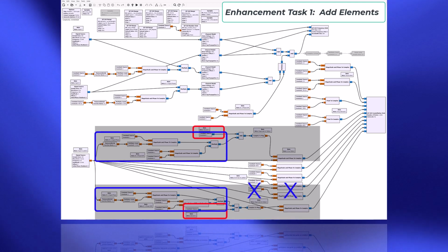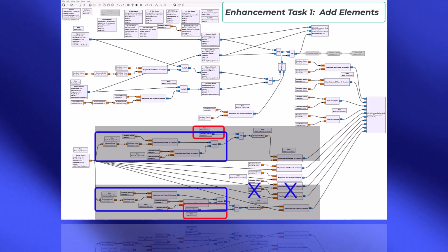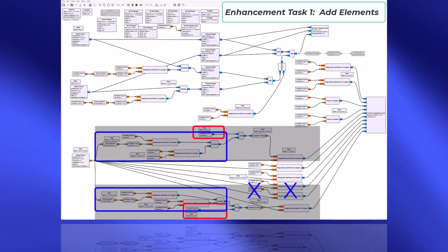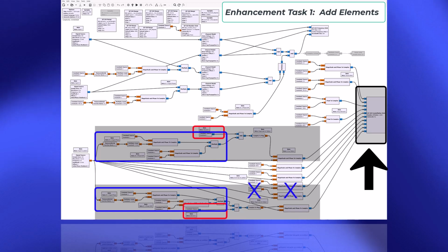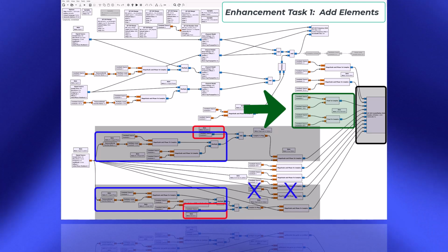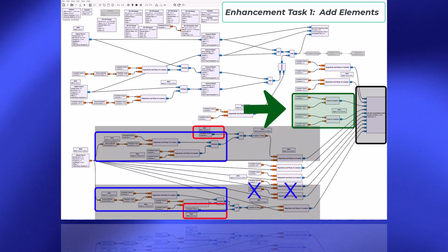There's a lot going on in this part of the flow graph, but the basic idea is that we're tracing out array patterns and concentric circles or grid lines on a polar plot that's generated using the QT constellation sink. Additionally, that constellation sink displays the element locations, which can be adjusted by using a slider to select the inter-element spacing, or the spacing between adjacent antennas within the array.